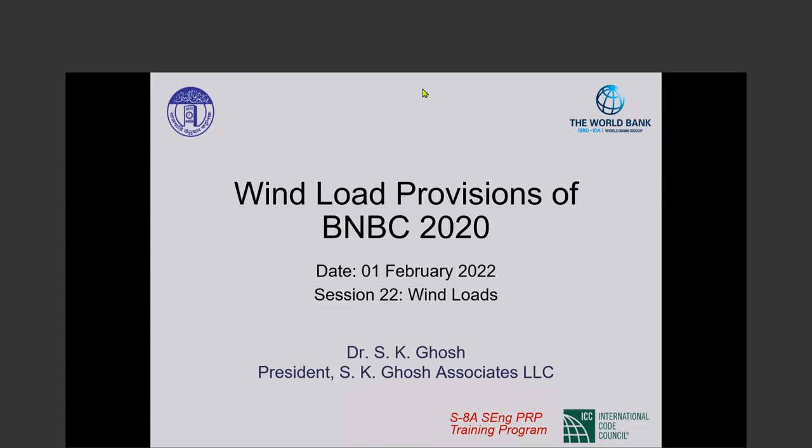Thank you, Bodhi, and good evening, everybody. Today's topic, as Bodhi just said, is the wind design provisions of BNBC 2020, which are based on ASCE 7-05, the 2005 edition of the US standard titled Minimum Design Loads for Buildings and Other Structures.